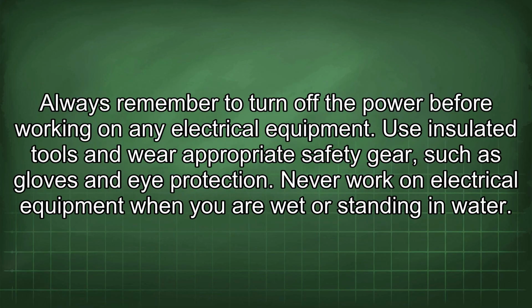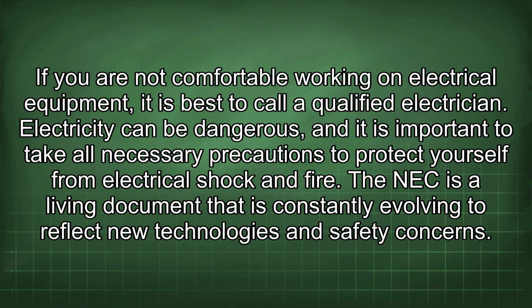Always remember to turn off the power before working on any electrical equipment. Use insulated tools and wear appropriate safety gear such as gloves and eye protection. Never work on electrical equipment when you are wet or standing in water. If you are not comfortable working on electrical equipment, it is best to call a qualified electrician. Electricity can be dangerous, and it is important to take all necessary precautions to protect yourself from electrical shock and fire. The NEC is a living document that is constantly evolving to reflect new technologies and safety concerns.